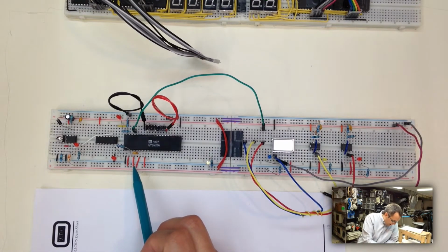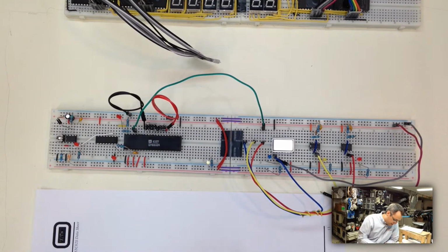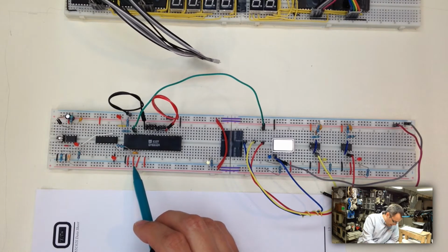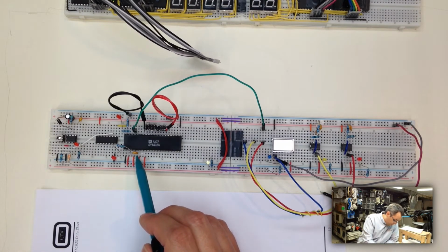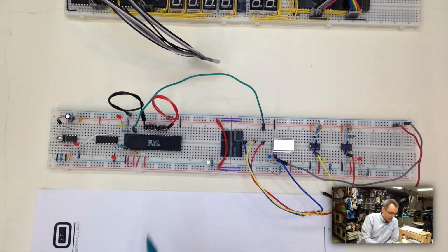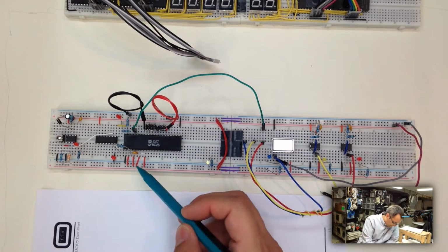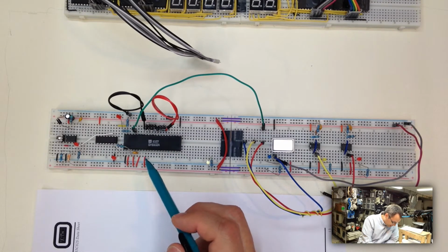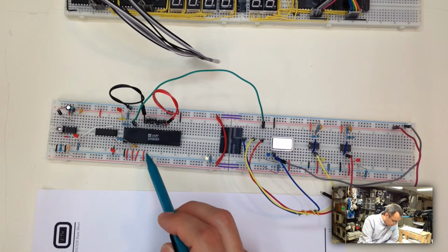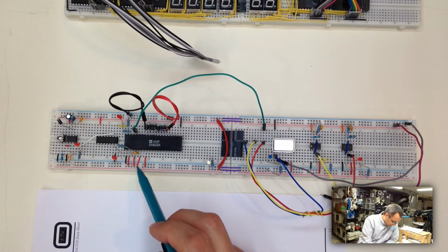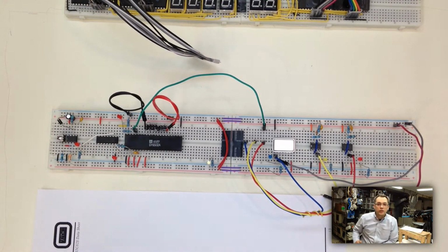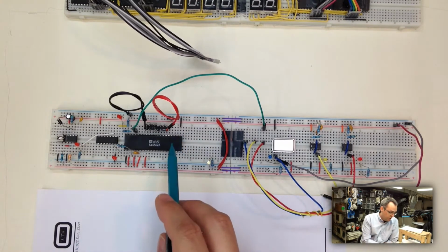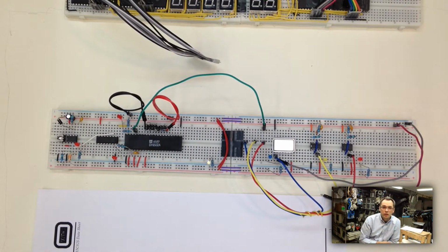This right here is our IRQB, as it's called. B meaning negative, according to the documentation. I'll just call it the IRQ line. The next one is an MLB, which we will not be using at all. This processor actually has nothing on that pin. This is the 65C02 that has that pin, but we'll be ignoring it. This is our NMI, our sync, and our VDD lines, the VDD being the actual power. This is ground. The sync line is basically left to float, and again, the NMI is pulled high. These IRQ and NMI are the interrupt request and non-maskable interrupt request lines. When those go low, it tells the processor to go fetch its reset vector and go jump off into la la land and respond to the interrupt that it's received.